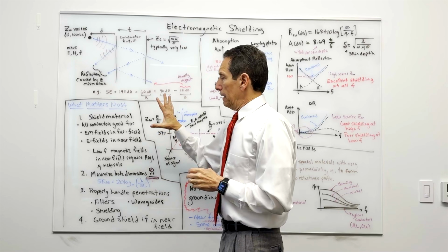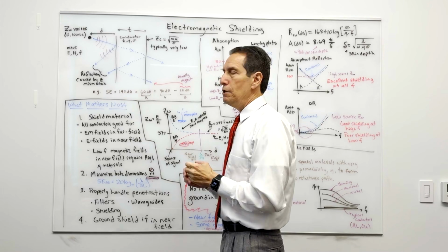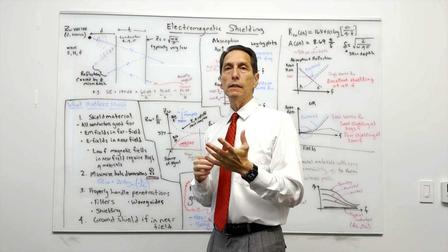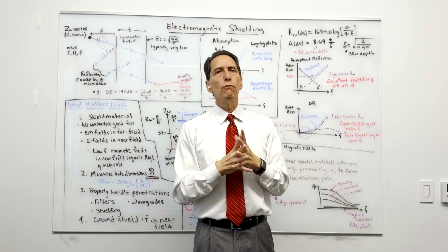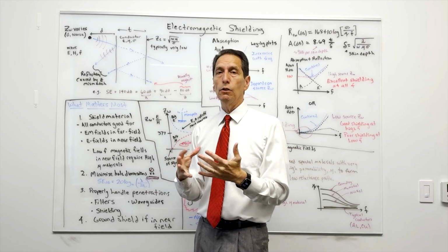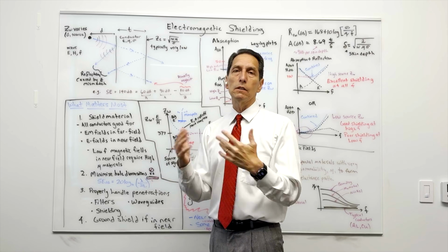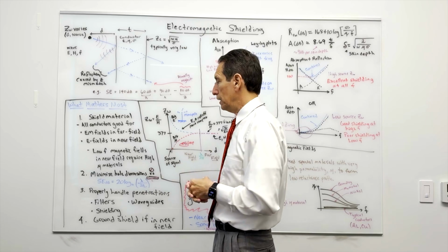So number 2, how do you make a shield really good? I didn't talk about any here, but what I mentioned was that in many cases, you have really great potential shielding that you can implement. What ends up compromising you are the holes and the slots and the various imperfections in your shield.